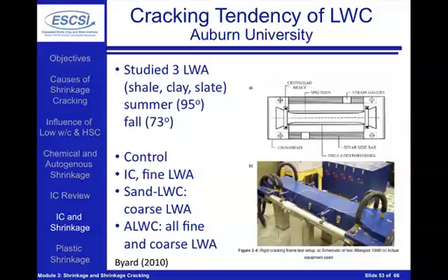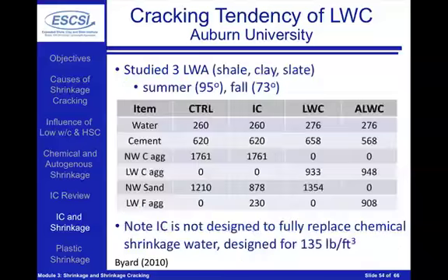Similar studies have been done at Auburn University under the direction of Anton Schindler, where he was using a control concrete, and then he was using internally cured concretes that might be used on a bridge deck, where these were sand lightweight aggregates or coarse lightweight aggregates or internally cured concretes. The main idea of this test is instead of using the ring, this is a linear sample, as you can see, sort of a dog bone shape, where the frame restrains the concrete from shrinking, much like your girder does, and you can measure the stresses that are developing in the system.